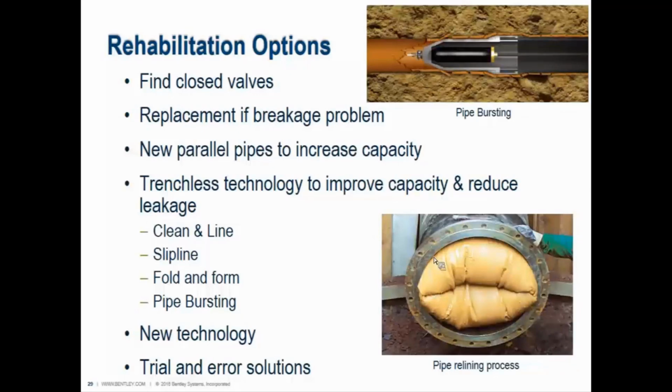One alternative would be looking at the physical alternative for diameter and C factor, and then you'd create a child of that and just simply change the diameter and change the C factor for those lines. And then compare those two scenarios and you can see really how well it's going to work for you.